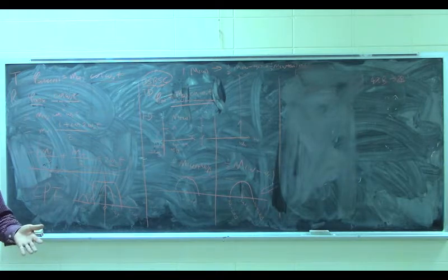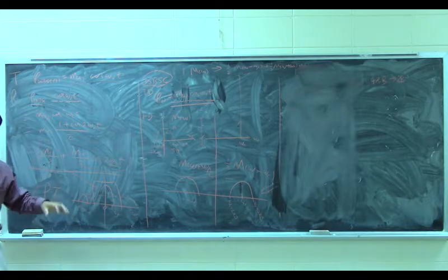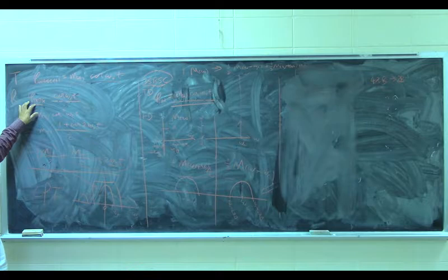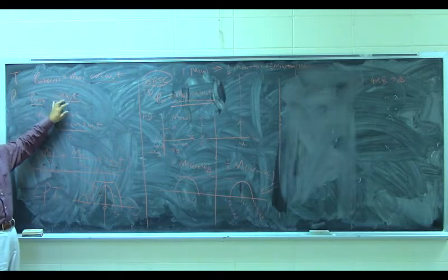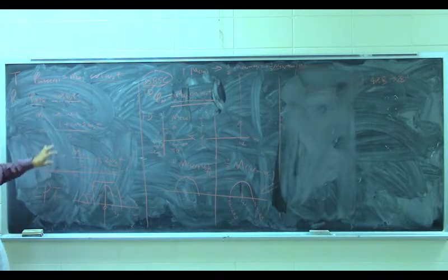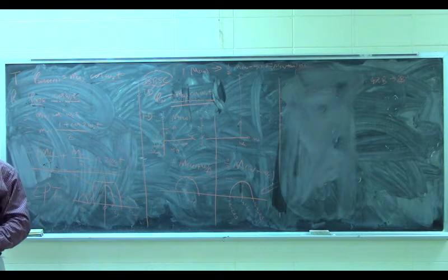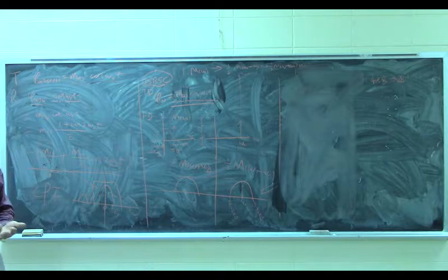Any questions? So at the receiver, what you need to do is multiply your received modulated signal with the carrier signal again, followed by a low pass filter. We get what we want. That is the explanation in the time domain of the demodulation process. Questions?